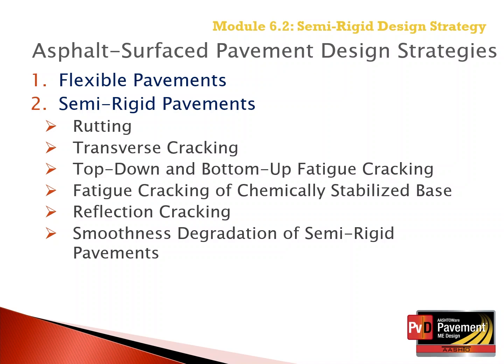This module will focus on the distress prediction models and transfer functions for semi-rigid pavements. These include rutting, transverse cracking, top-down and bottom-up fatigue cracking of chemically stabilized base layers, reflection cracking, and then smoothness degradation of semi-rigid pavements.